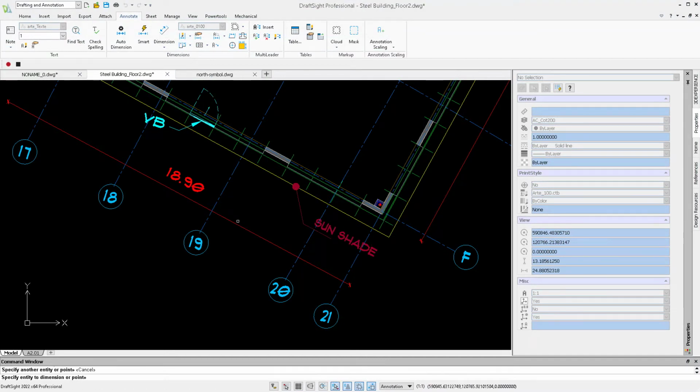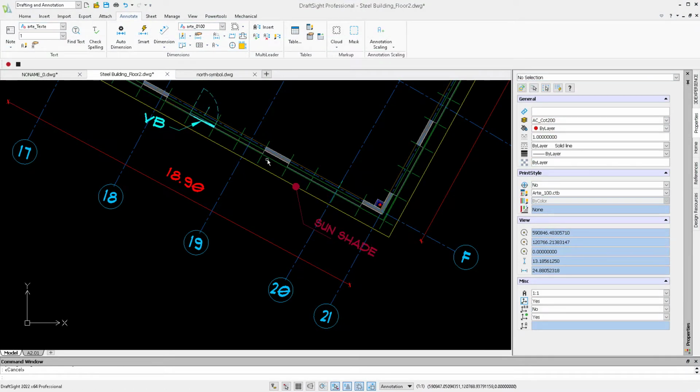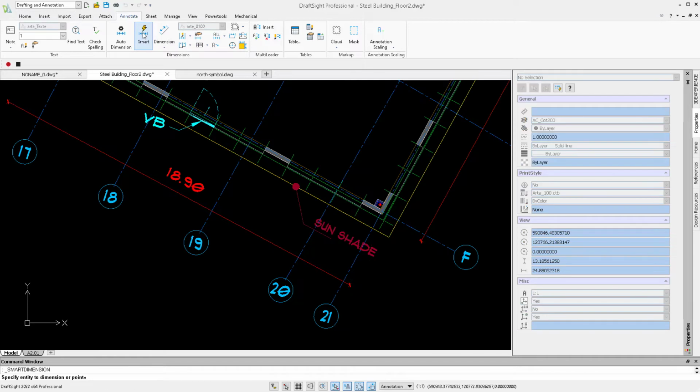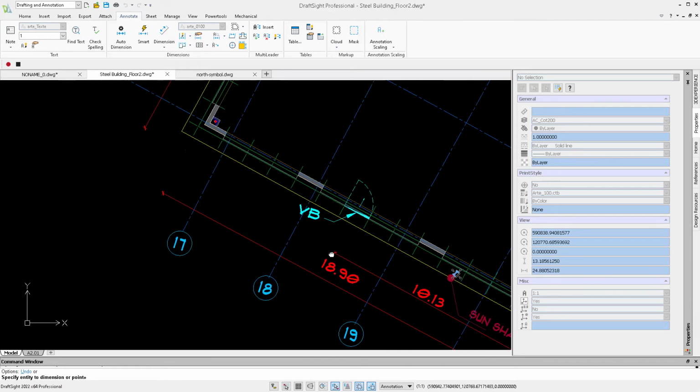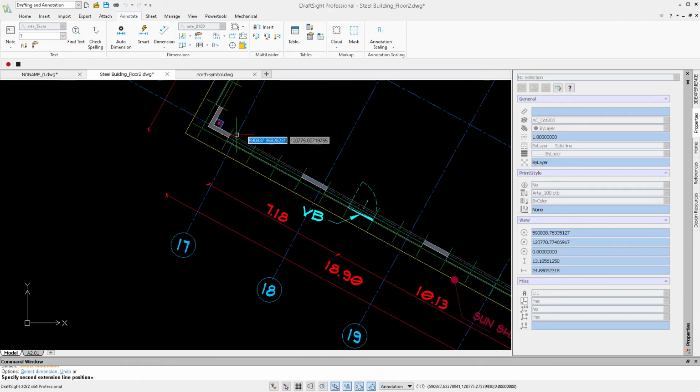Thank you, Bertrand. So here we're at the tail end of this one drawing for the floor, and what we're going to be doing is adding a couple dimensions to this wall to locate the center of this doorway. So I'm using Smart Dimension. It allows me to pick 2 points, and it can give me a horizontal, vertical, or aligned option. We're going to choose aligned, then I'm going to use the Continue Dimension command just to pick a third point and drop that last dimension in there.